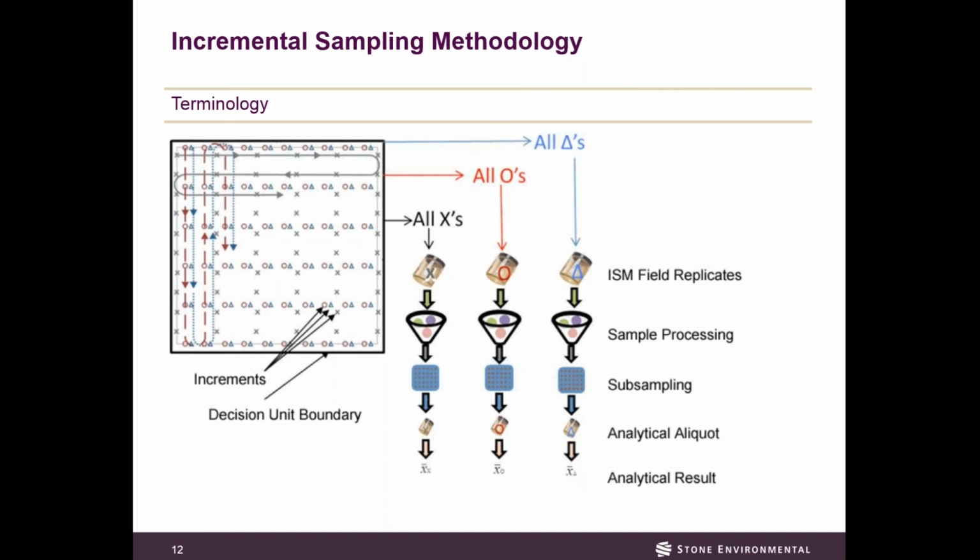So you've already seen this figure. This is out of the ITRC's 2012 guidance, and it just describes the different steps. As I said, I'm the practitioner. I've got the cookie tray and some of the other tools that we use. So what this represents, every one of those shapes represents an actual discrete sample that was collected. Usually it's between 30 and 100 actual grids that you take between 3 and 5 discrete samples from every one of those squares. And we'll go into detail further on that.